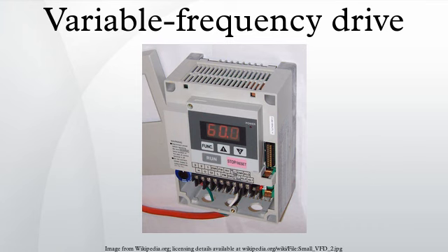In variable torque applications suited for volts per hertz drive control, AC motor characteristics require that the voltage magnitude of the inverter's output to the motor be adjusted to match the required load torque in a linear volt per hertz relationship. For example, for 460 volt, 60 Hz motors this linear volt per hertz relationship is 460/60ths equals 7.67 volts per hertz. While suitable in wide-ranging applications, volt per hertz control is suboptimal in high-performance applications involving low speed or demanding, dynamic speed regulation, positioning and reversing load requirements.